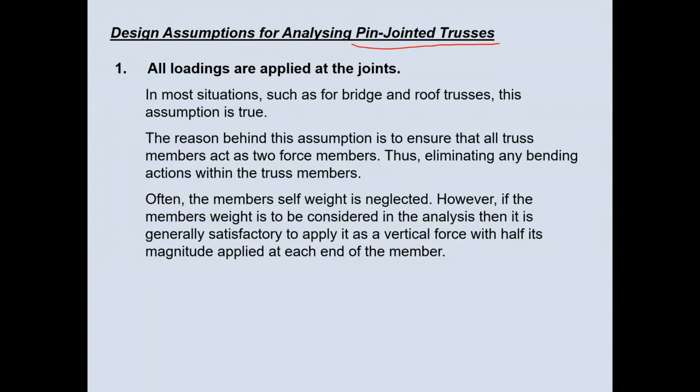In real life, truss structures are connected through gusset plates, but the gusset plate's resistance toward rotation is negligible compared to the forces that each individual bar member can take axially, in compression or tension. This assumption is quite applicable in general, be it a bridge or roof structure.